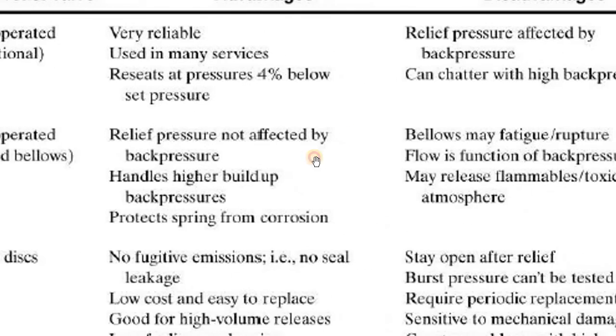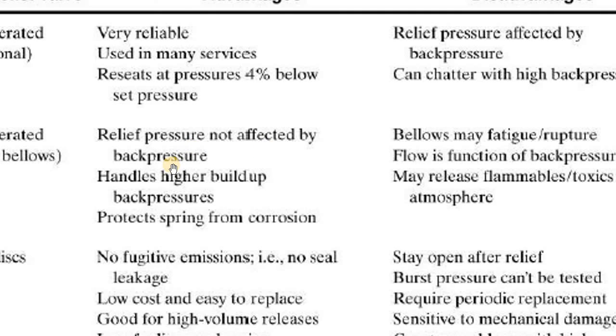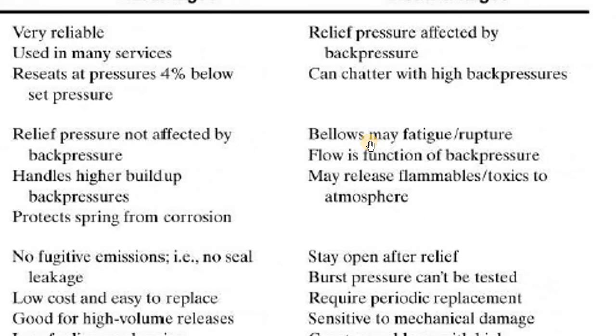What about the balanced bellows? It's not affected by backup pressure because it is balanced, and handles higher built-up pressures because it balances both sides. That's why it handles backup pressures really strongly and protects the spring from corrosion. And here, what are the disadvantages?